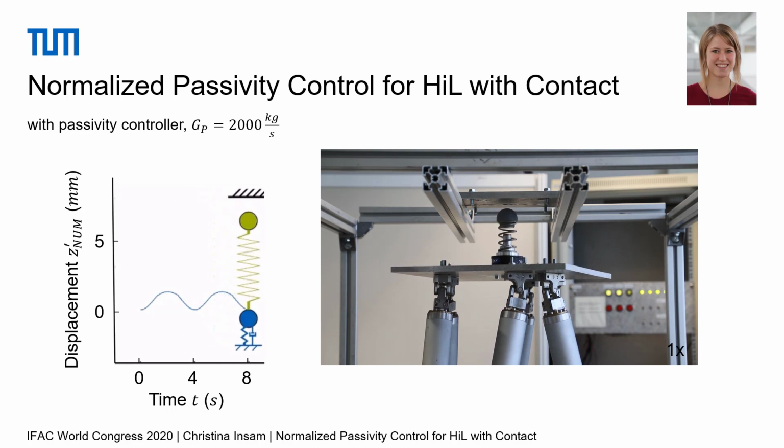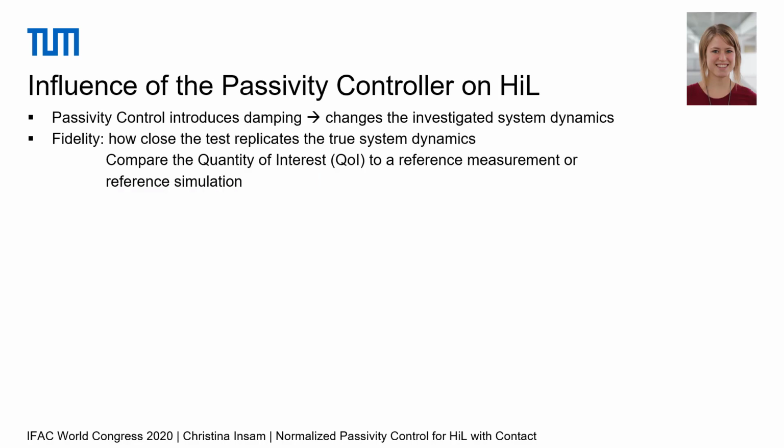As you can see, the oscillations can be damped, and the passivity controller proves successful also in this application with contact. You might agree that the video looks nice and that the passivity controller does its job. Nevertheless, we investigated the influence of the passivity controller on the hardware-in-the-loop test in more detail.